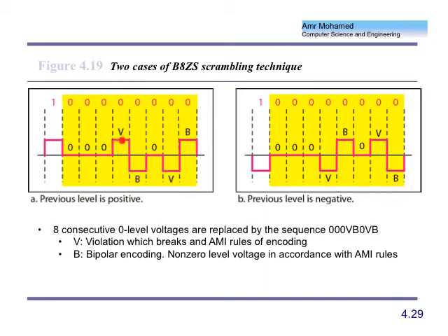by giving me a positive voltage level, not 0, not negative, because if it's 0, then I did not fix anything. If it's negative, then the receiver will say, this is a legitimate voltage level and it's opposite to the previous non-zero voltage level, so I'm going to interpret that as 1. The receiver will say, okay, so this is a negative voltage level and the previous one was positive, therefore this is 1. I don't want this to happen because the original bit is 0, not 1.